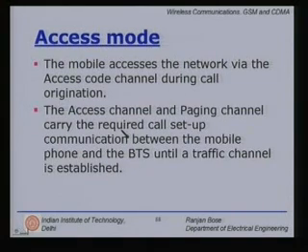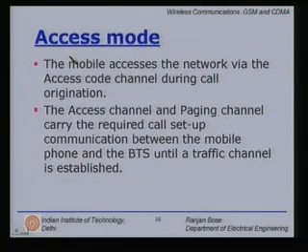All the time, like in the idle mode? No, in idle mode the code is not decided. At that time, we only talk about the power that I require to use and the time synchronization. Time synchronization is important even to carry out the communication regarding which PN sequence to use, because all the communication is being done based on codes. Right? So, timing and power are essential requirements for communication, not necessarily voice, even control information.